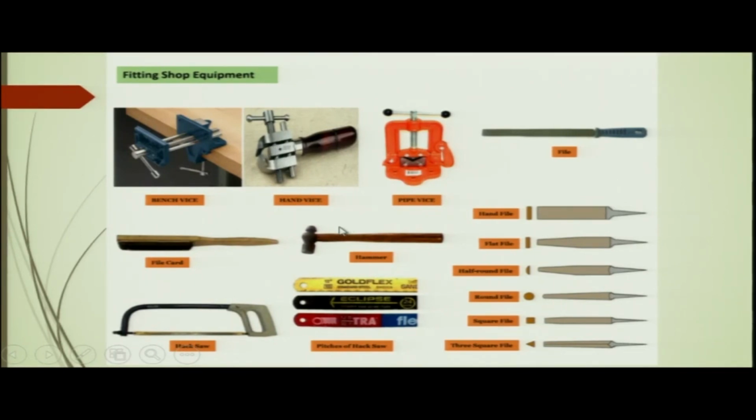All right. Now this is the pipe vise. Pipe vise is also very popular. You can see on the roads where the workers are cutting the pipes or making thread on the pipes, they have to be mounted on the vise, so that there is no movement of the pipe with respect to the tool that you are using. So here also there is a lead screw.